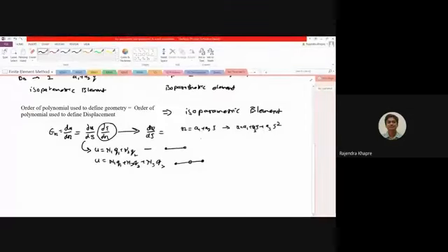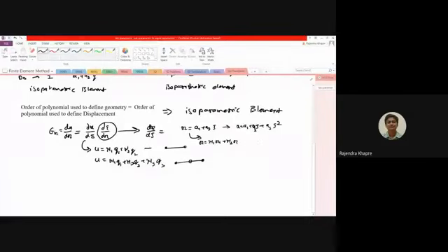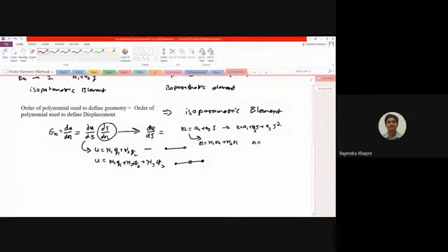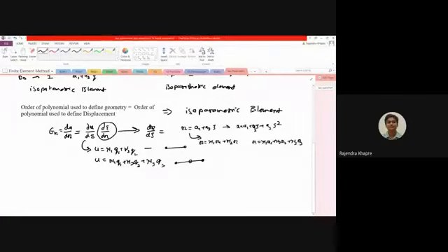So as a result of this, what you are going to get is x equals N1 x1 plus N2 x2 in case of 2-noded bar element. In case of 3-noded bar element, x will be something like N1 x1 plus N2 x2 plus N3 x3, okay.